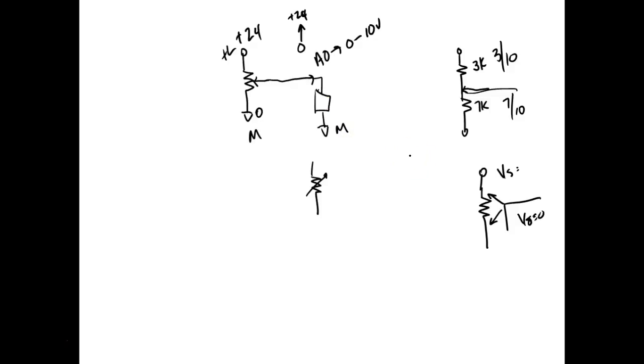That makes sense? So I'd have to do this on my analog sensor, but normally on your analog sensor, it's going to be referenced to common anyway, right? You understand? And then I would power the sensor up, and then the sensor would give me the range. And the normal range for an analog sensor is 0 to 10 volts.